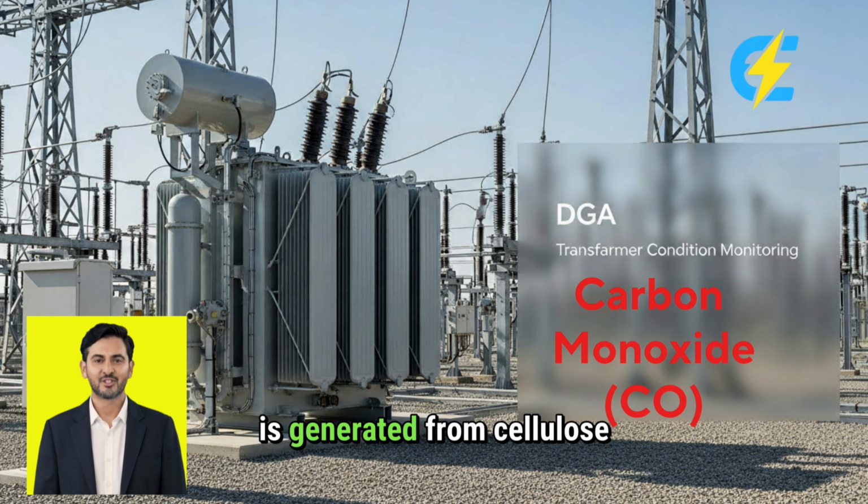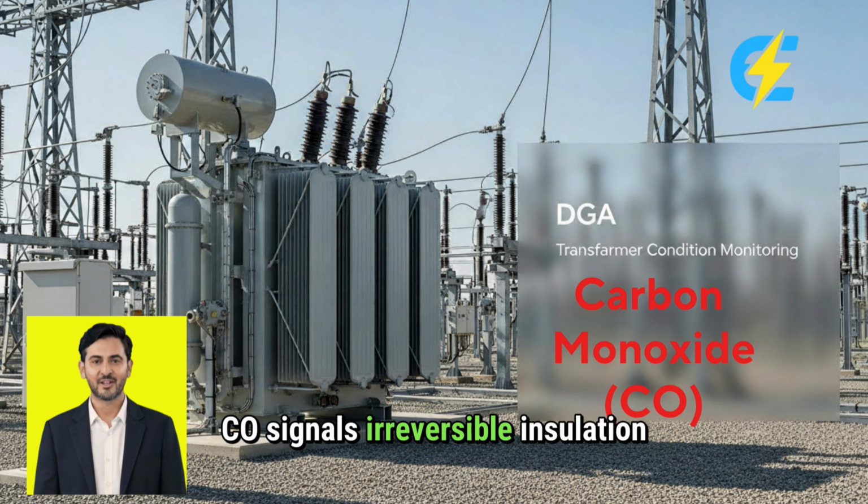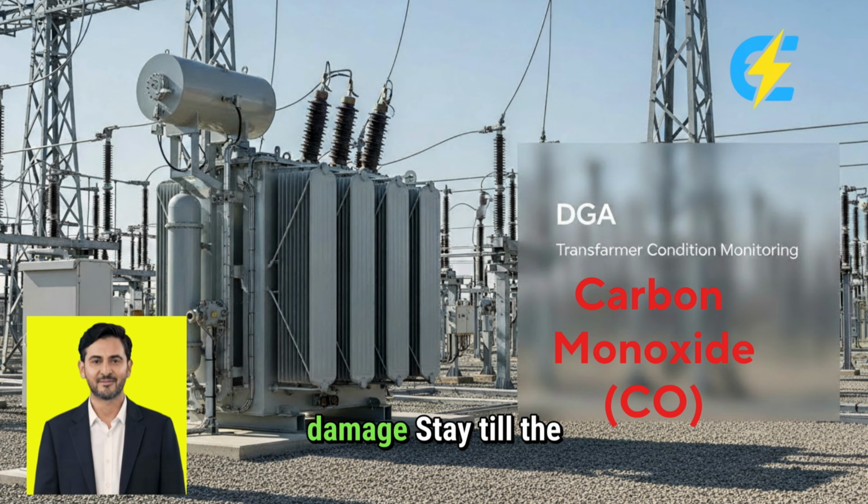Why CO is generated from cellulose paper. How thermal stress breaks down insulation. Difference between CO and hydrocarbon gases. How CO trend predicts loss of mechanical strength. When CO is acceptable, and when CO signals irreversible insulation damage. Stay till the end, because CO tells you not how the transformer is running, but how long it will survive.